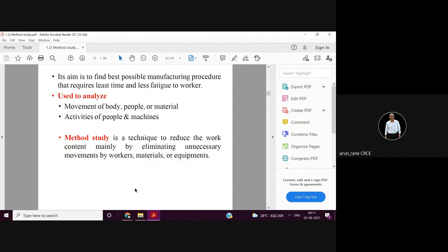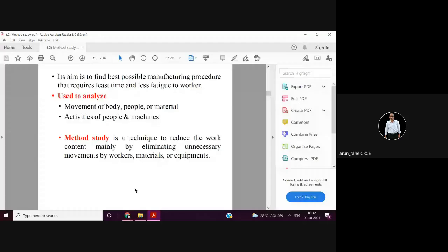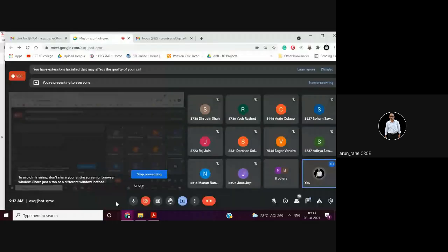Like suppose, differential mounting. Differential mounting is one workstation where the differential is mounted. Tire mounting, that is another workstation. Your body mounting, where the body is loaded and clamped. So like that, at every workstation you have to see, as an industrial engineer, that the work content is the same and the activity time is almost balanced. And that is what is called line balancing.